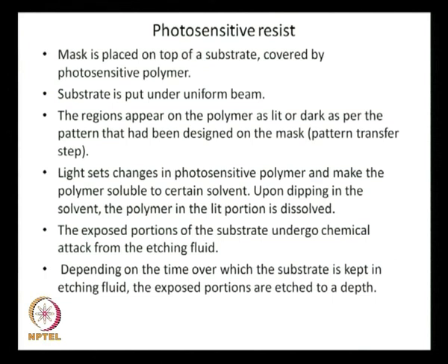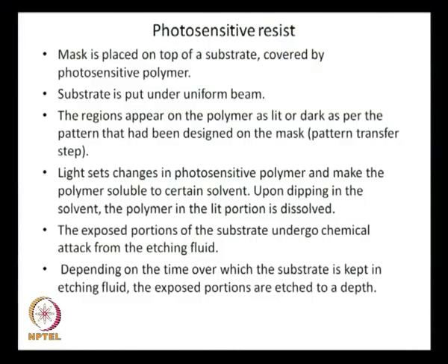So, when you dip this substrate into the etching fluid after the dissolution of the polymer, the etching starts, but it happens only in the places where the substrate is exposed. Depending on the time over which the substrate is kept in the etching fluid, the exposed portions are etched to a depth. So, gradually you see the etching taking place and a depth develops in that channel.